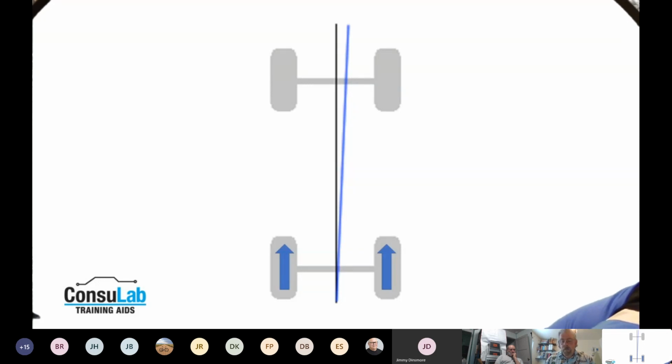One other thing in some of my recent research is they're talking about tire slip angle. Ackermann has a lot to do with slip and tire slip, and now they're actually looking at that too, calculating slip with a module to determine how much slip is actually happening in corners. So that's another input to the computer for the autonomous driving things. There are things on vehicles now that can actually calculate the slip angle.